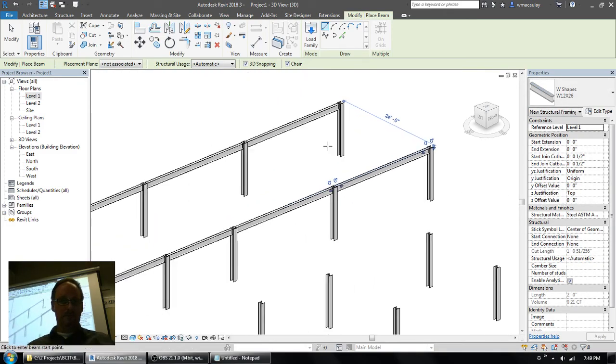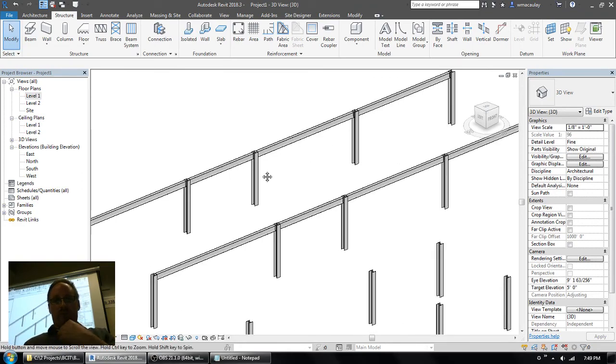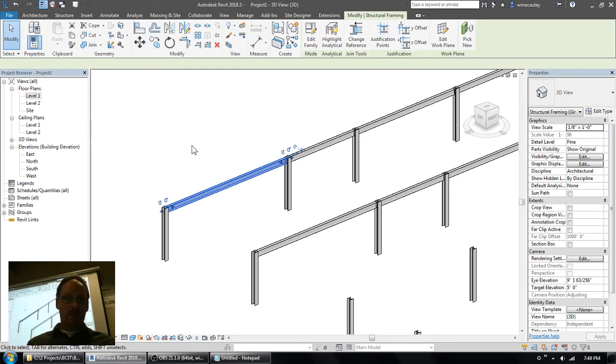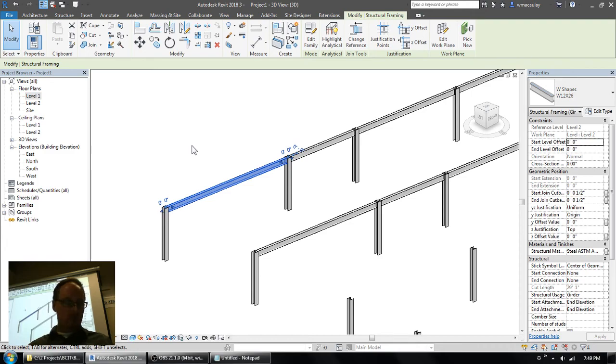There. And we're going to talk about the 2 different kinds of beam handles. Now beams can be placed on grids in plan. You can see that in page 2 there in the notes. I like the visual confirmation of what my beams are doing, so that's why I will do my beams in 3D rather than drawing them in plan.